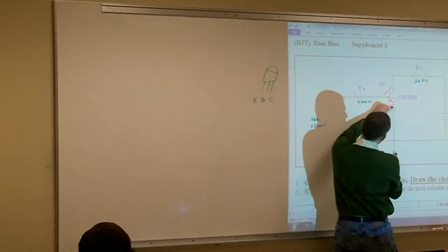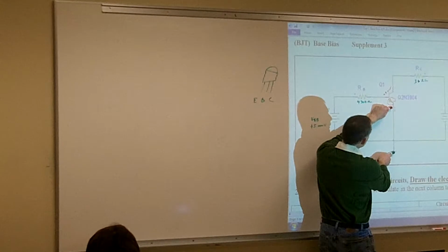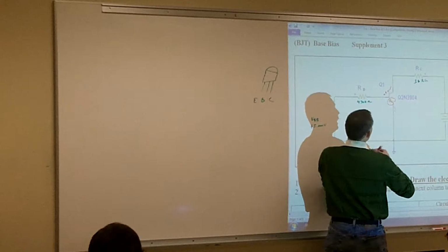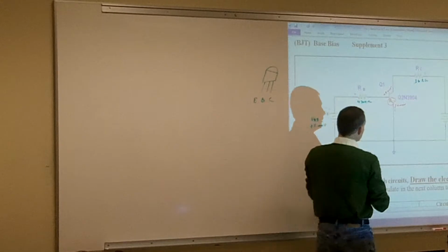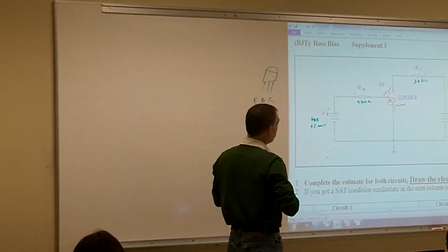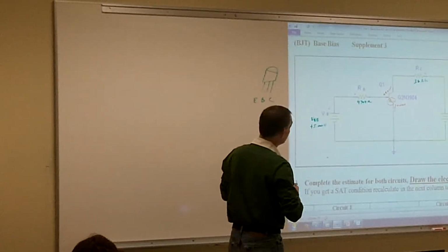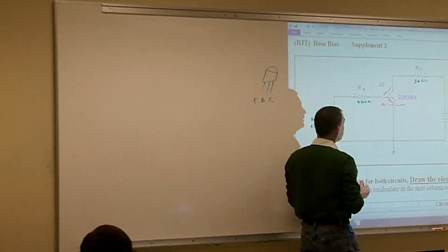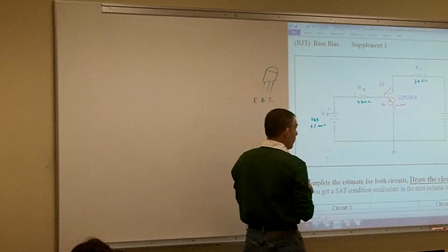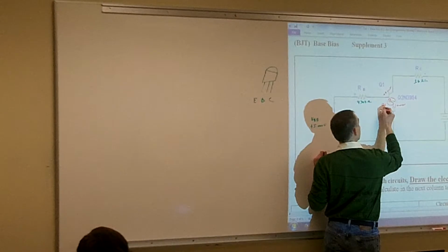And on the emitter side of my transistor, what do I measure for voltage? Plus or minus 0. So then we have to determine whether that base to emitter is going to be a go or a no-go. That's going to be a go. And if it's a go, it's just like any other solid-state device: it always takes its voltage first. And that voltage across the base to emitter is going to drop how much? 0.7 volts.